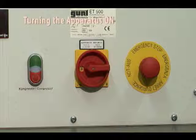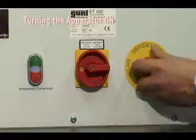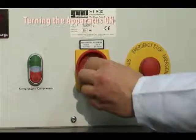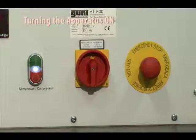Turning the apparatus on requires 3 main switches on the switch cabinet. First, switch the whole system on by pulling the emergency button and turning the master switch on. Turn on the compressor by pressing button I on the compressor switch.